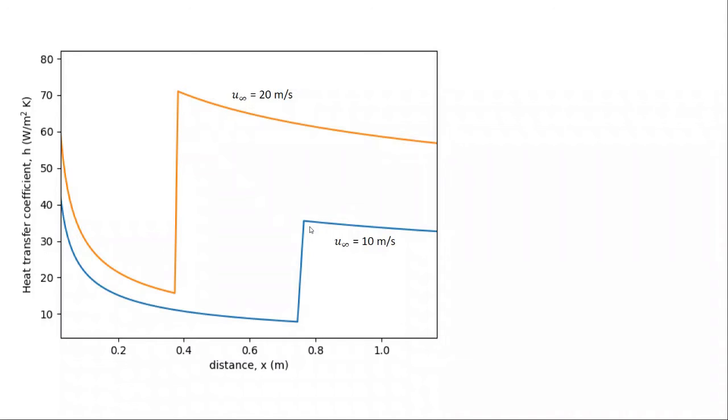So we move from a laminar boundary layer where the flow is very smooth to a turbulent boundary layer that is stirring the flow and providing a great deal of mixing, and that is dramatically enhancing the heat transfer coefficient. And we know that the transition between laminar and turbulent for a flat plate, as we discussed in class, occurred around a Reynolds number of 5e5.